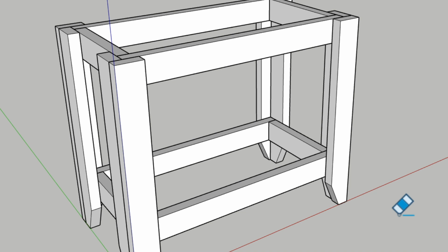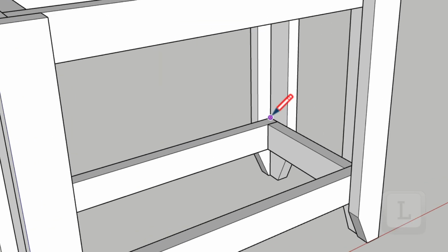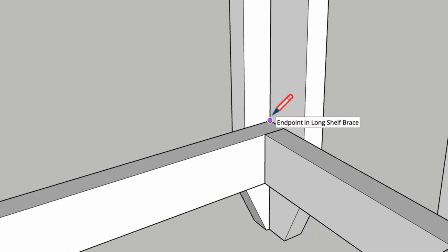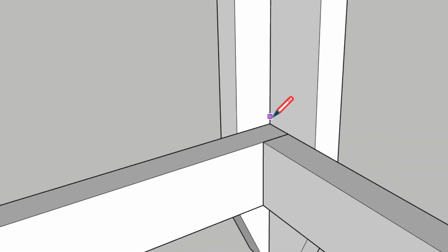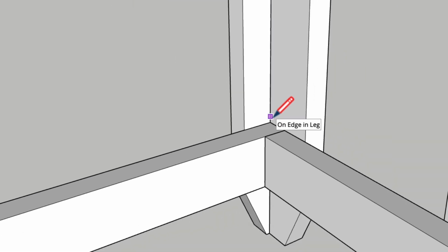Press the line tool. We actually need to go draw something real quick, so let's press L for line, and then zoom in on this corner. We could try and use a rectangle, but it's going to be easier to draw out here with the pencil or the line tool. So click on this corner, move up.